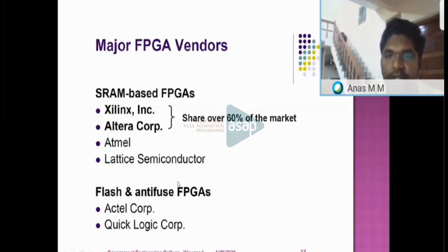After manufacturing the microcontroller, it is impossible to change its internal architecture. We can only give a program according to the architecture. Suppose the architecture inside the ATmega328 supports a 10-bit ADC, and you are designing a system that needs a 12-bit ADC. At that moment, it is impossible to use the ATmega328 for that system.